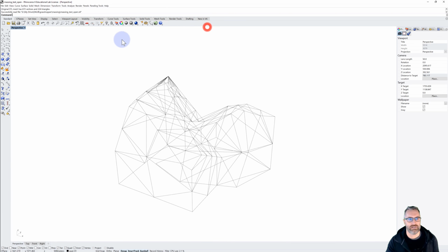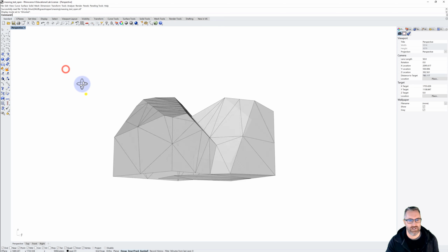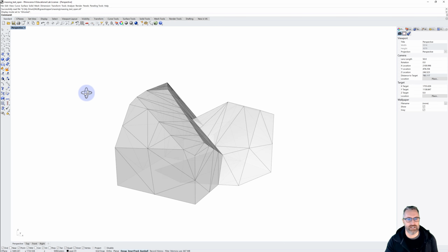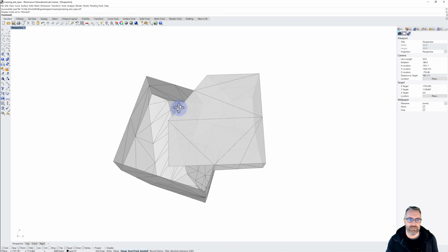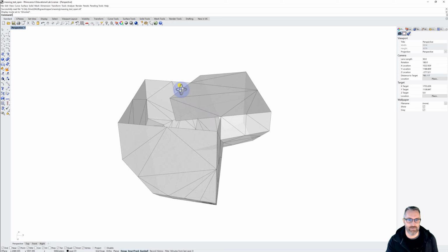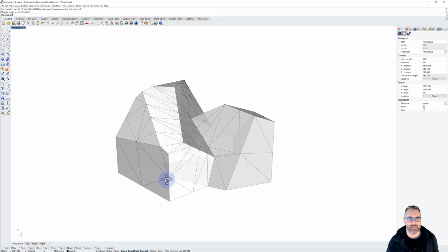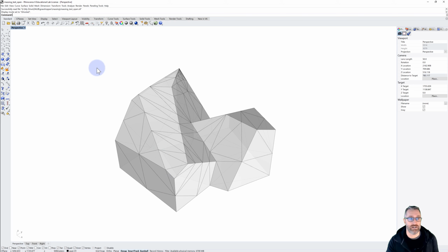And let's see, I'll look at this in perspective and maybe turn on the ghosted view. And so we can see that it's open; I deleted that one face on the bottom. What we want to do is test, and I keep using this term, watertight model, completely solid. This is not watertight, because if we filled it with water and turned it over, the water would fall out. And so watertight means that it needs to be a completely closed volume.